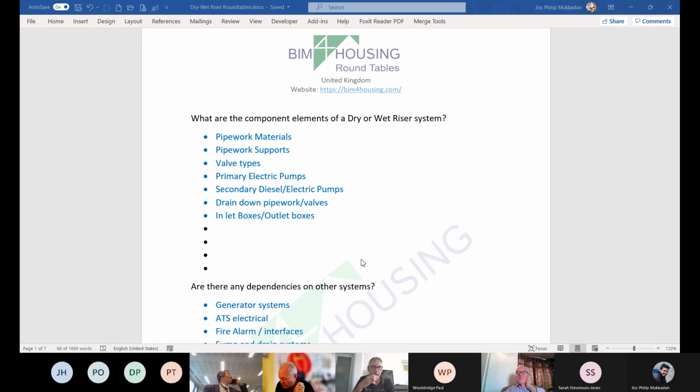Well, I know the Plumis guys quite well. I've seen fire tests and had chats with them. Some people think water mist is a well-established technology since it's been on the market for 30 years, but in some ways it's still very immature, with standards still being developed, for even just the basic components. And unfortunately, a lot of the installers are not third-party accredited, nor are their components third-party tested. So Plumis is actually one of the ones trying to do this properly, although their particular design, their philosophy doesn't fit in with the way the standard is written that we have for water mist in this country.